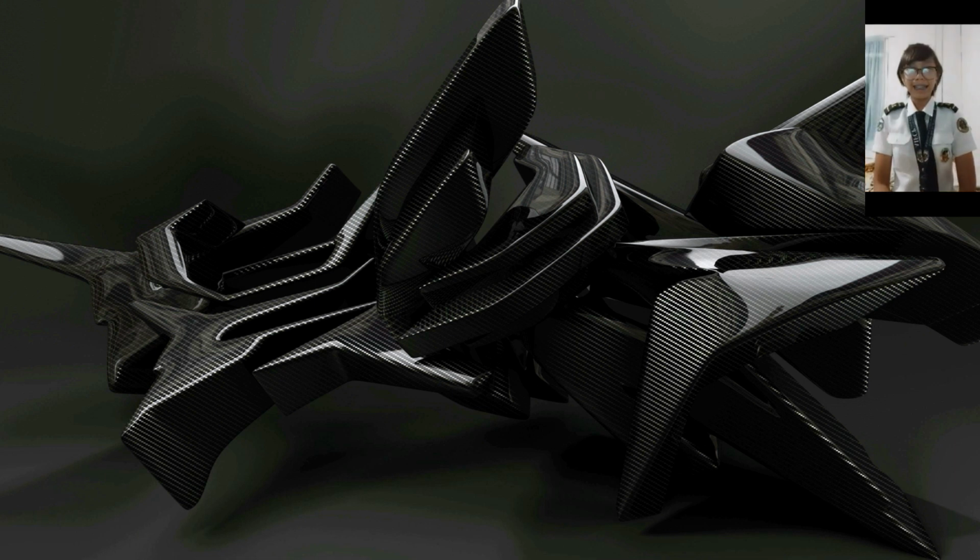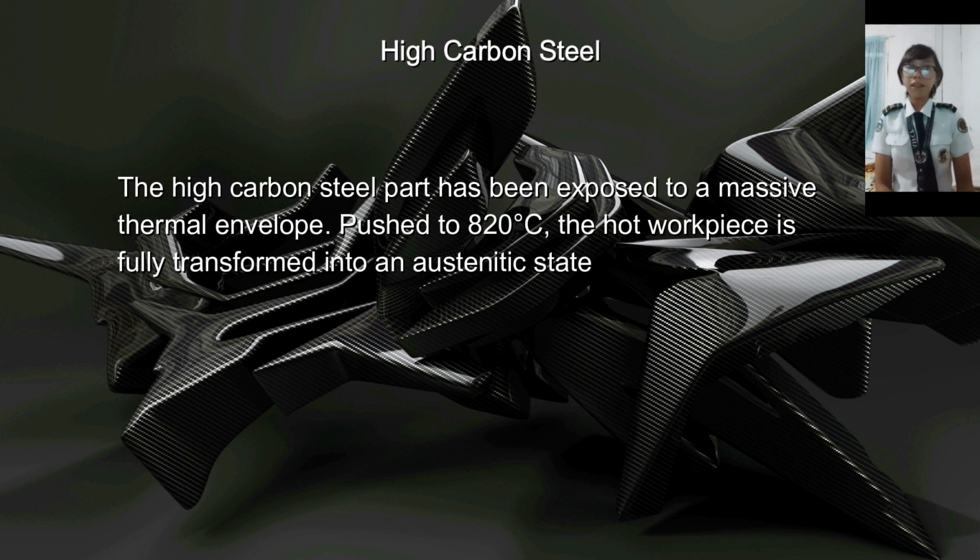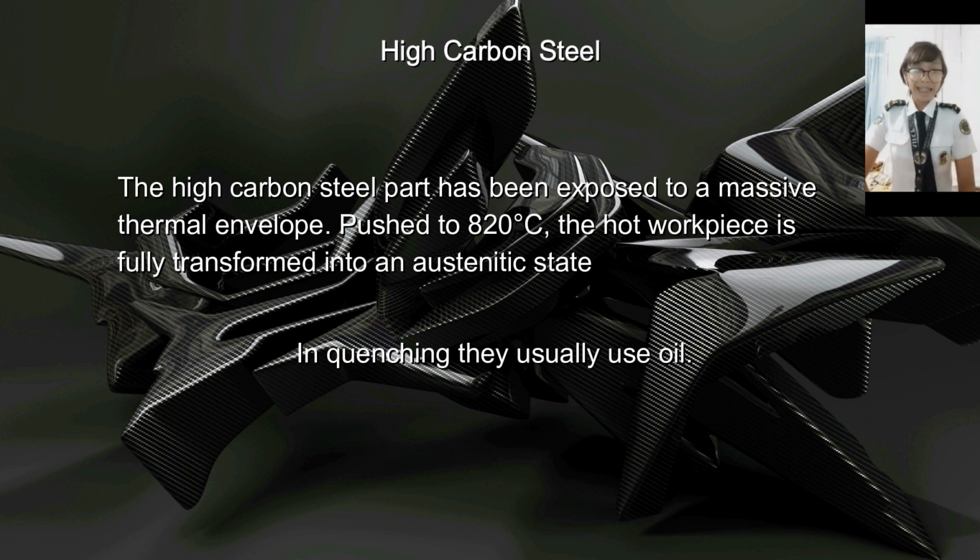Lastly is the high carbon heat treatment. The high carbon steel part has been exposed to a massive thermal envelope pushed to 820 Celsius. The hot workpiece is fully transformed into an austenitic state. And in quenching, they usually use oil.